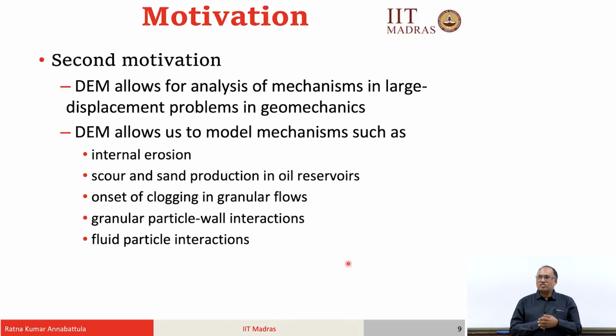And it also allows us to model various mechanisms such as internal erosion, scour and sand production in oil reservoirs, and clogging in granular flows. When does a granular flow clog? When does a particle flow in a chute stop? And what happens to particle wall interactions? If you have a fluid, what happens to the fluid particle interactions? All these things can be accessed.